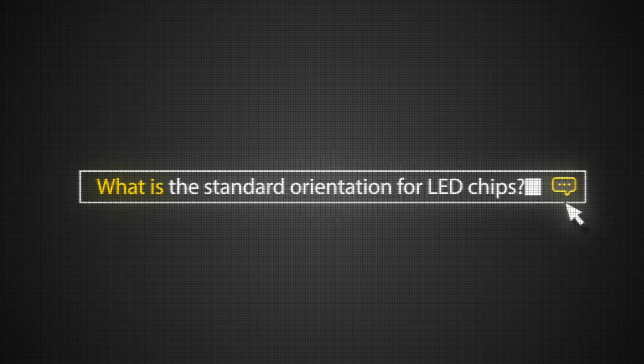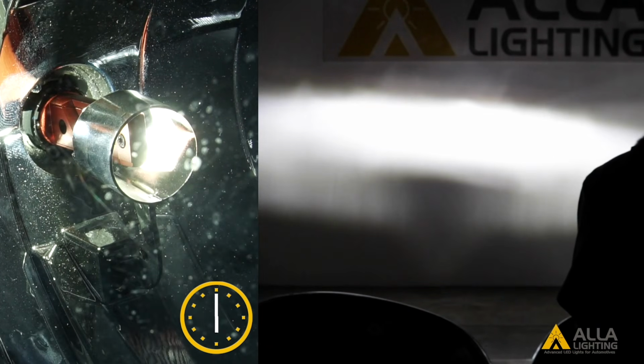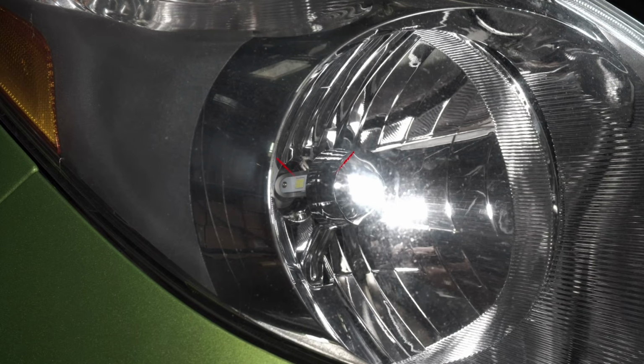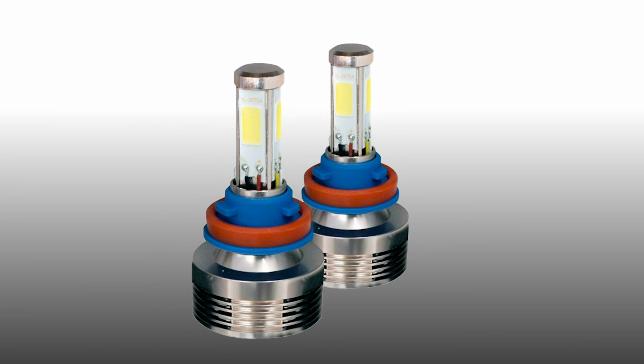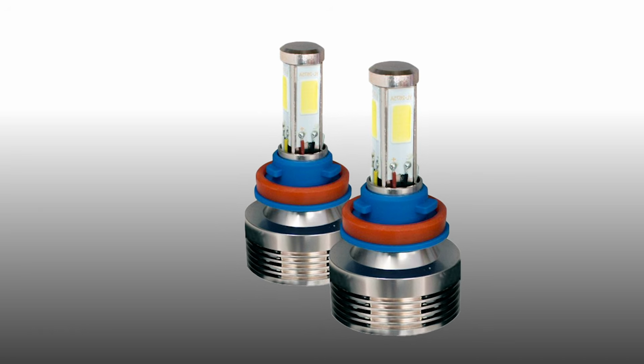What's the orientation of the LED chips? Is there any standard? It depends. If you have a two-sided LED headlight, then vertical is usually the best. For single filament, for dual filament. If you have a three-sided LED headlight, then the deeper chip is facing downward. If you have a four-sided LED bulb, or with chips all around, the orientation doesn't matter because nothing will change when you adjust it.